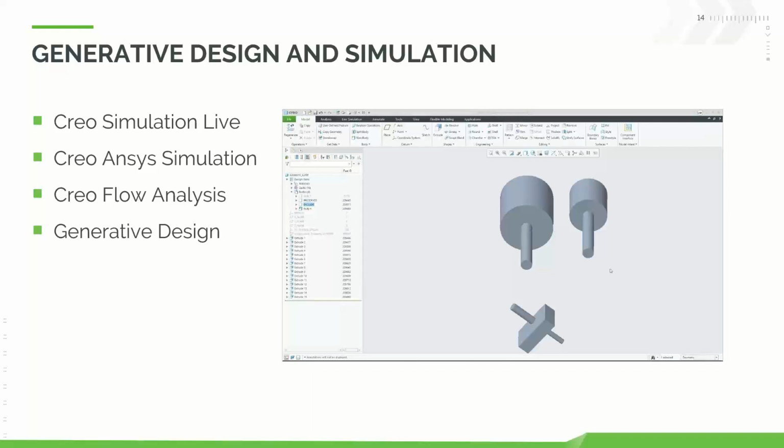And one other nice to have here is the ability to run a single initial simulation before you start into a generative optimization. It essentially acts like a sanity check for you. Make sure that your loads and constraints all look right, and then you can do your generative run. So just avoid spending time or spending effort on the wrong things. Just let you know something is good to go before you spend any more time on it.